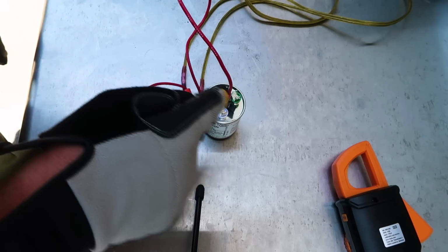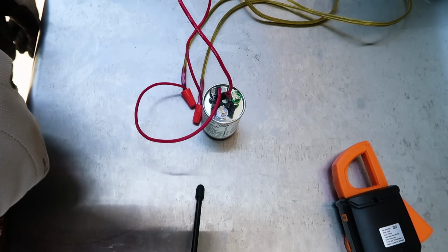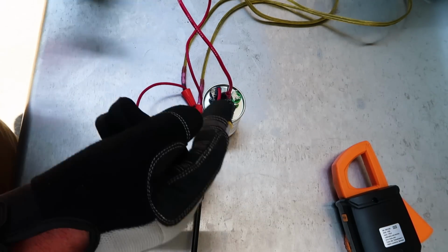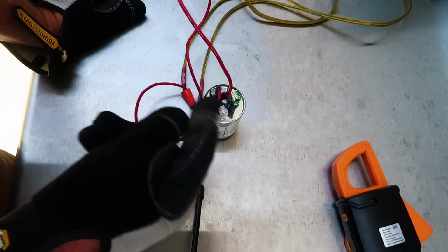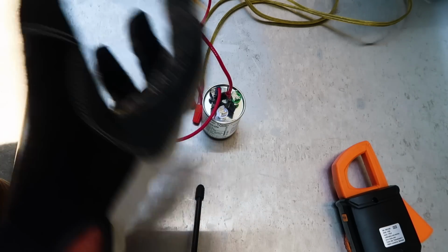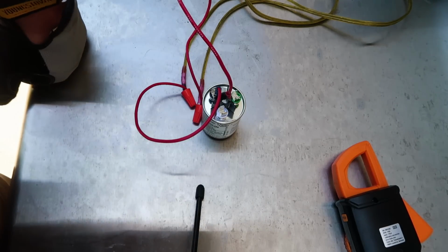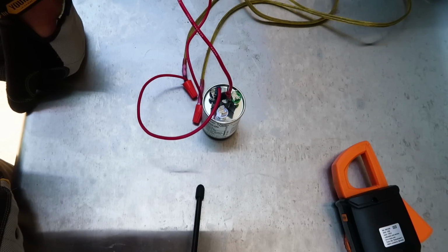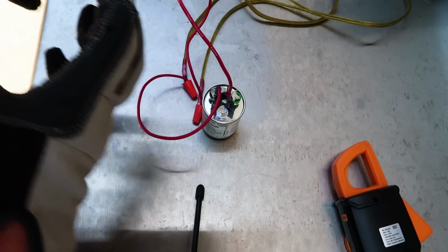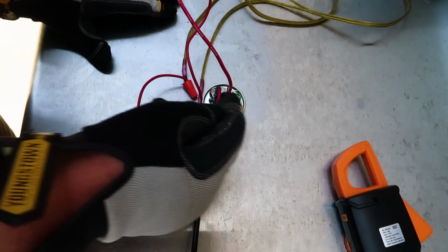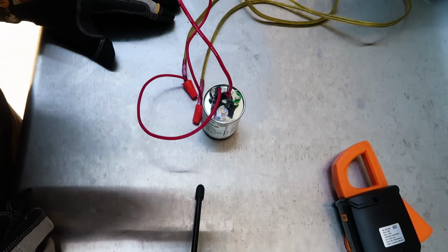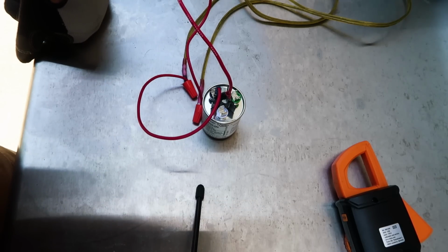But there's no actual connection in between these terminals. These two terminals aren't shorted together. You have a plate, and then you have an electrical field that builds up on either side of the plates that attracts and then repels the electrons in and out. So this thing is like a little electron balloon that's just constantly filling up and discharging. And there's a differential charge across those two terminals. What will happen if I apply a higher voltage to this?